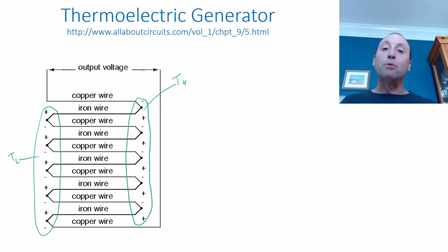then each of these couples would generate a voltage, and by connecting them in series, all those voltages would add to each other, and we would measure a higher voltage. That's the idea behind a thermoelectric generator. It's just a number of thermocouples wired in series to provide a voltage to power some piece of equipment.